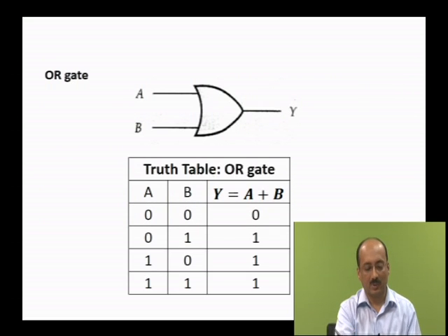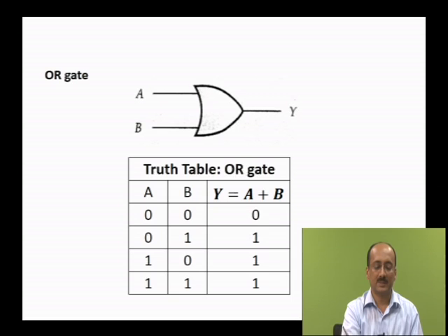We come to logic circuits now. This logic circuit basically works on the principle of Boolean algebra. You will have three basic gates: OR gate, AND gate, and NOT gate. The first one is OR gate. It is such a gate that its output will be high. Generally, when you say high, you write 1. If it is low, you write 0. It is not that 1 means 1 volt, 0 means 0 volt. So, this gate is such that its output will be high even if one of the inputs is high, as you can see here. If both inputs are high also, it will give high.